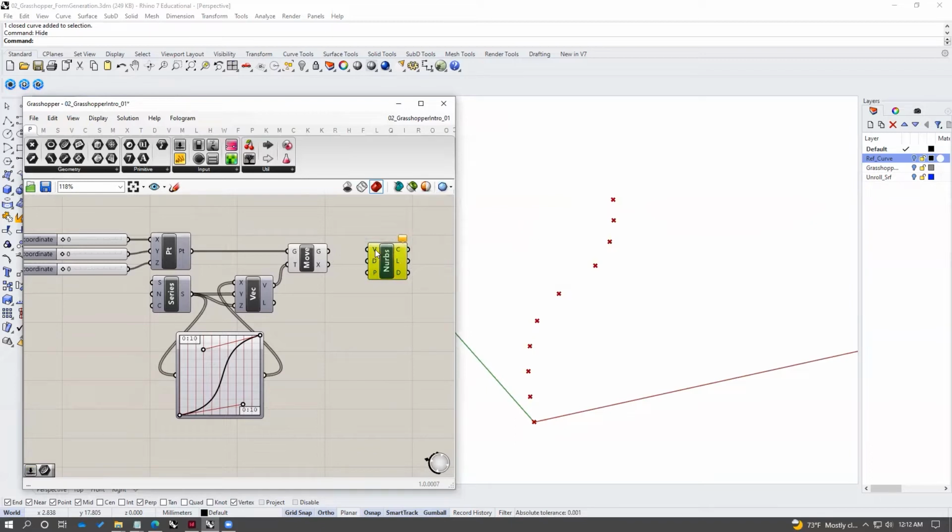This is going to take, similar to a polyline, input vertices. So we can plug those points into the input vertices. And then it's going to take an argument for the degree of curve, which degree 3 is fine for now. So we can now in real time adjust this curve based on our point positions.